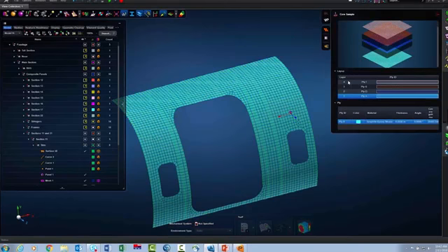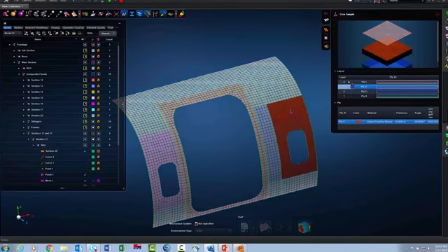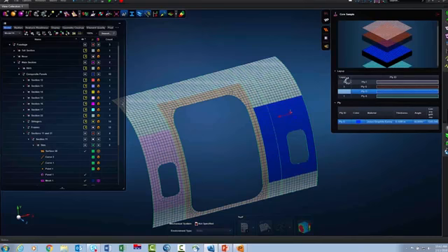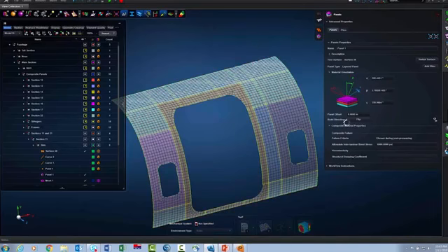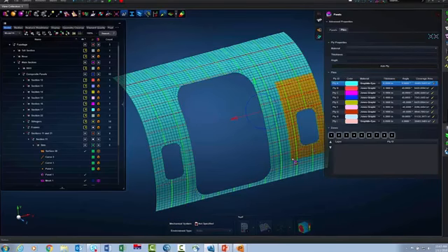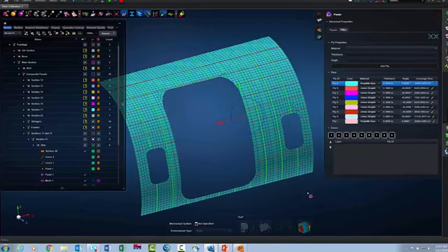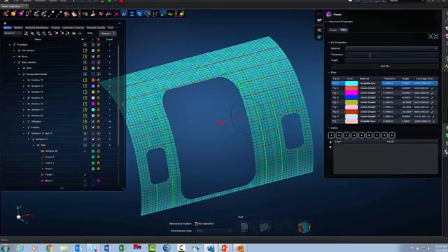So I'll plant the core sample tool, and then I can quickly review what the layers are, and I actually see what the individual plies are, not only in the area that I've sampled, but if they extend beyond that, I get that feedback as well. And if this is an area that I need to modify, I just double click and it automatically takes me right back to the panel tool so that now I can start making some modifications to the layup in this particular panel. Okay?